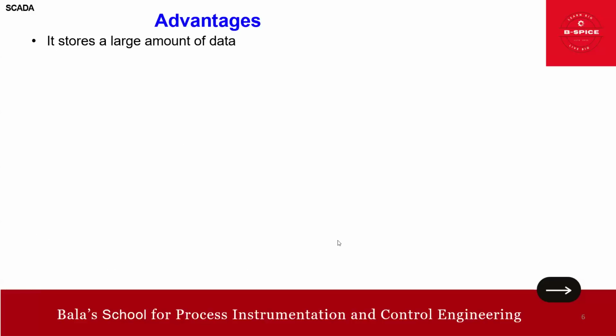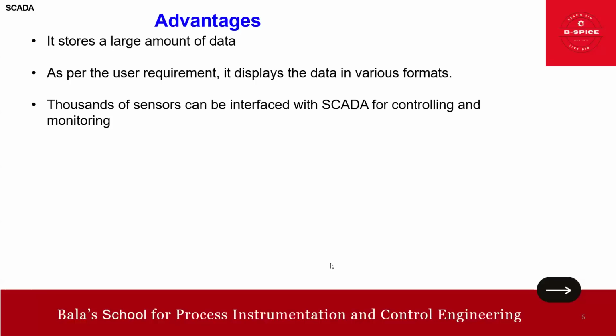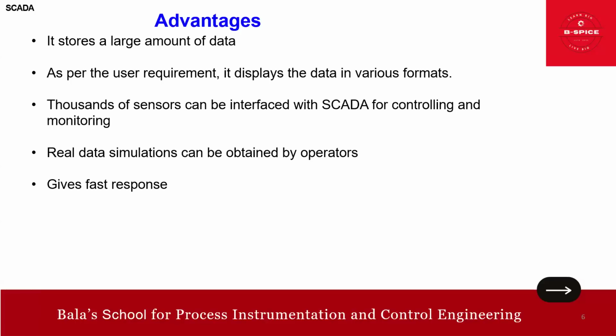Then a few more to add on: it stores a large amount of data. That is one of the key advantages. As per the user requirement, it displays the data in various formats. If you want graphical, if you want a data format, all these options are available. And of course, thousands of sensors can be interfaced with SCADA for controlling and monitoring. Real data simulation can be done by the operators, and it gives a fast response.